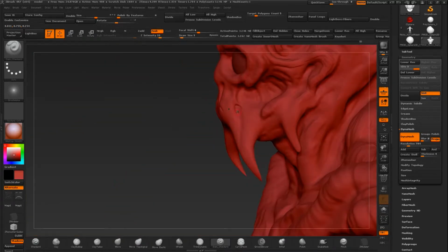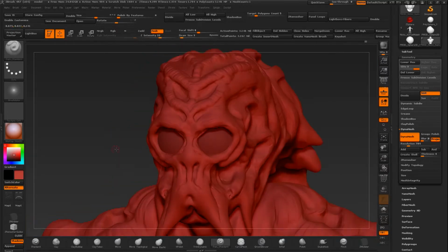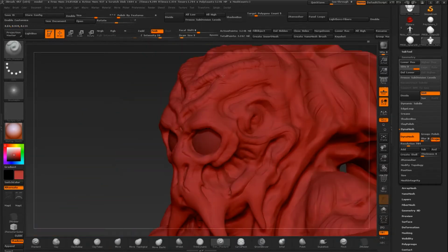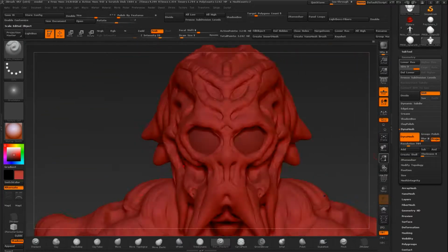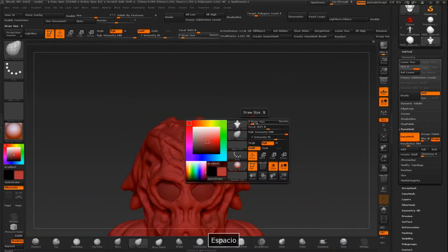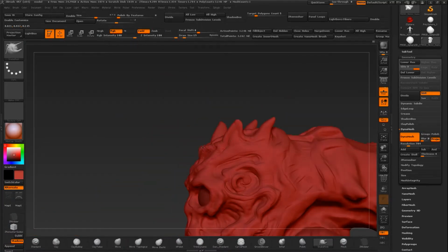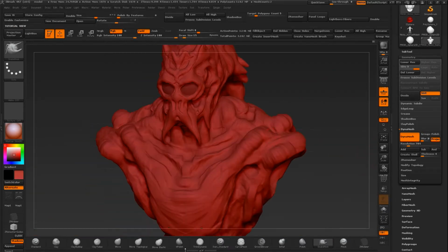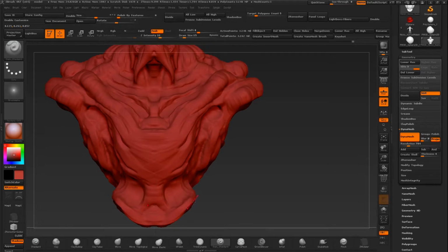Another important tip is related to the size. If you're going to create a quite big model, you can hollow it out. Why? Basically because there's no need to use that much material. It's totally unnecessary. So if the object is big, hollow it out. But there's also an exception or something you need to pay attention to. Let's use as an example the model of a house with the door open.